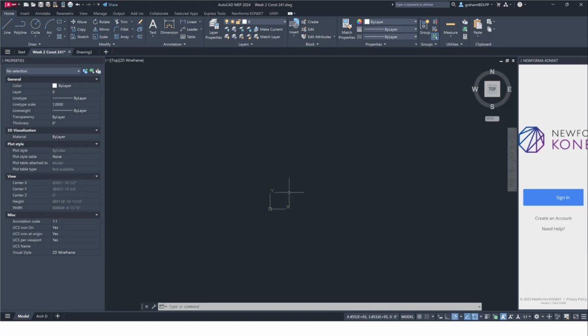All right, great question though. So I'm going to zoom, Z, enter, E, enter, bring this back. And I'm going to draw my line from the top left-hand side of the post to the top of my 6-inch line, and then one more down to the other corner of my post and hit escape.